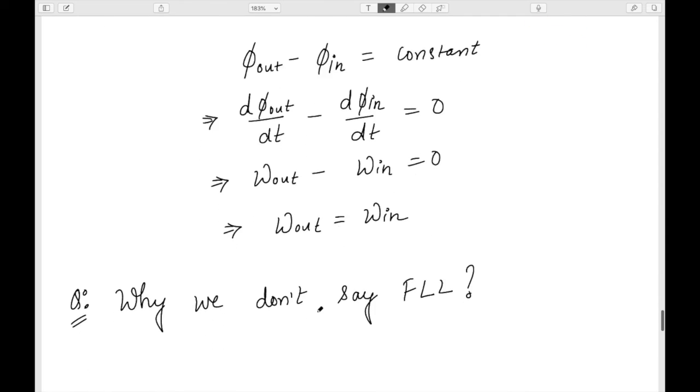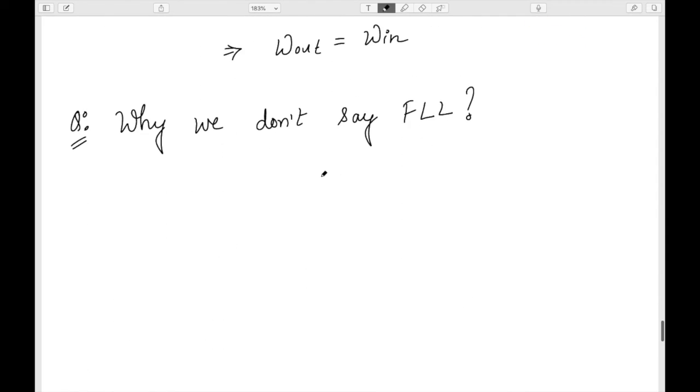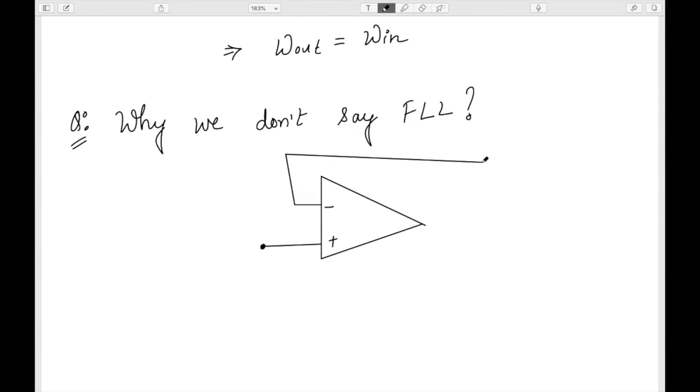The reason is very simple. When we are designing some op-amp, maybe a source follower op-amp, let's take this as an example. This is very nicely explained in the Razavi book as well. If I am a voltage follower, ideally V out will be the same as V in. But in actual cases we may not get that, because of the offset.